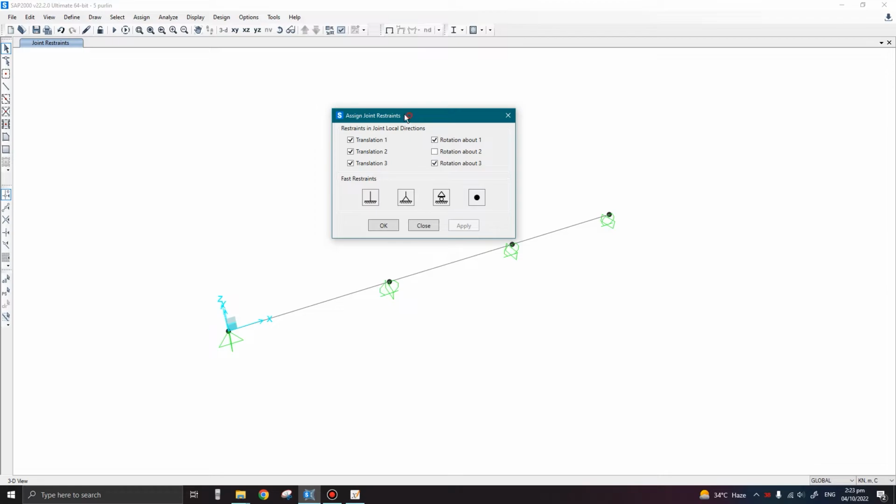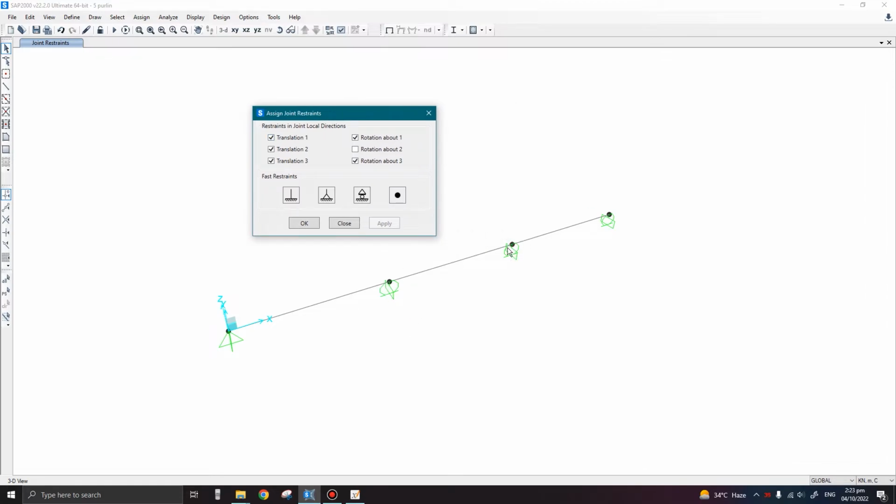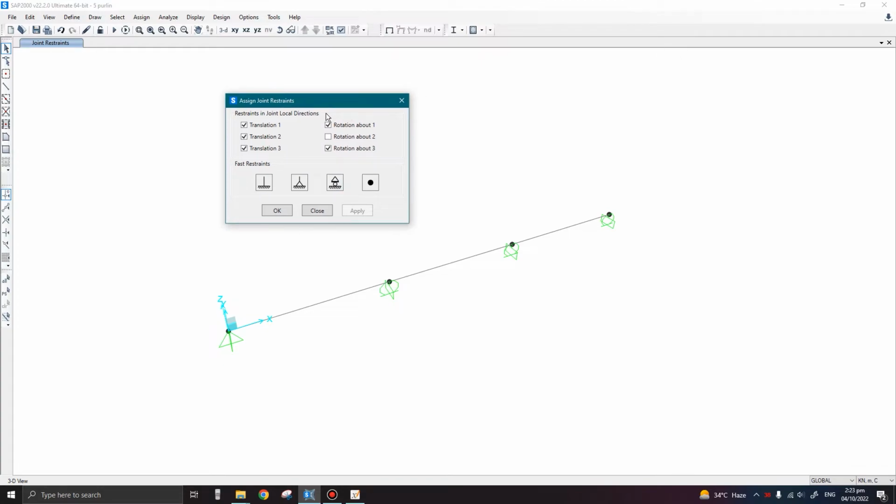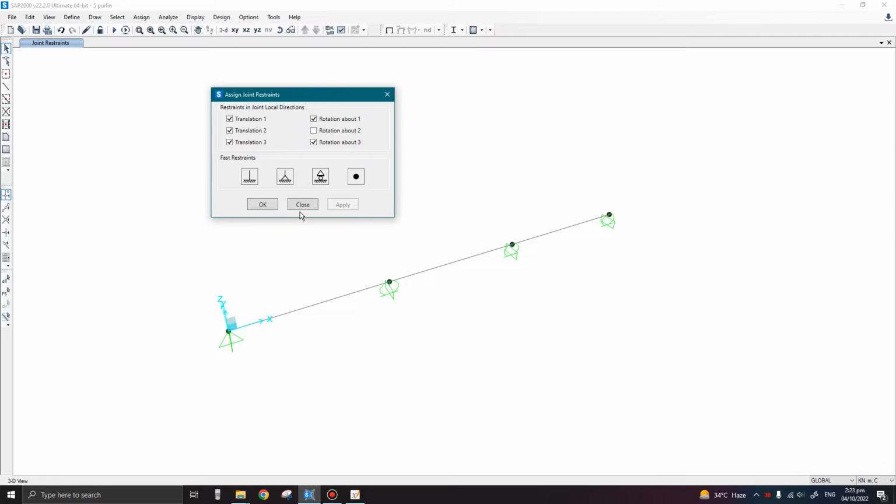We will discuss this arrangement in some later lecture, why I have given this roller support. I'll just briefly discuss here that the support conditions are provided to cater for the temperature loads, because usually due to temperature loads there is expansion and contraction in the member. So that's why I've kept it as roller in this direction, whereas fixed in the other direction. We will discuss this later when we go to the temperature loads.